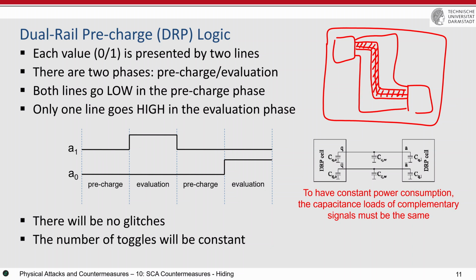As I said, I do not expect you to have experience in chip design, but these metal layers connect inputs of one gate to the output of another gate. They go to the metal layers, not in the semiconductor. There are many different layers. When you build a silicon chip, there are a lot of metal layers at the top that help you to route these signals. They may go to different layers, and then they will have very different shapes. And if they go to different layers, then they also have different capacitances. And the idea is to route them very similarly as a fat wire, and then divide the wire into two parts.